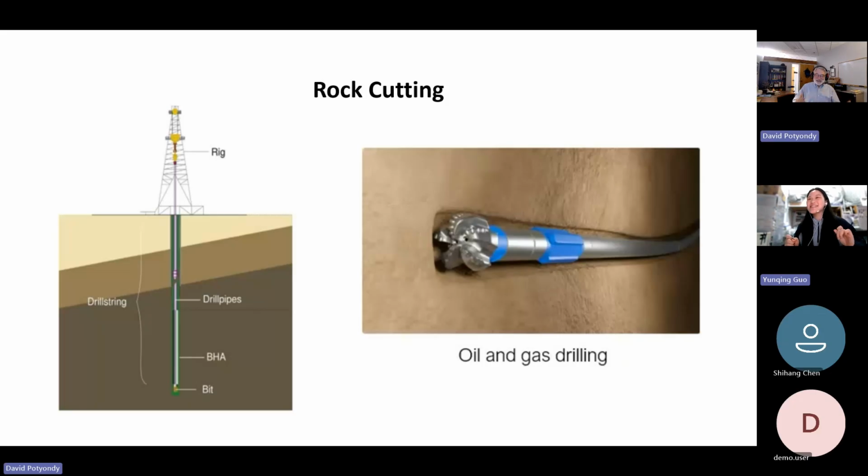You have a free surface. So this would be, for example, in a rock mechanics laboratory, you would take a cylinder of rock, and you would put it between two steel platens and you would squeeze it. And the surface is free. They call that an unconfined compressive strength test. Then what they can do is they take the same specimen, but they put it in a rubber jacket, and then they put hydraulic oil pushing against it. So we call that confinement.